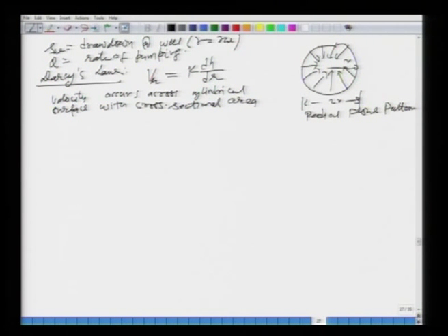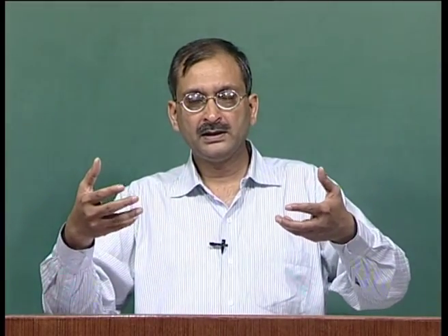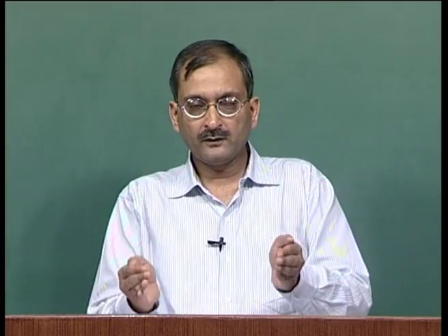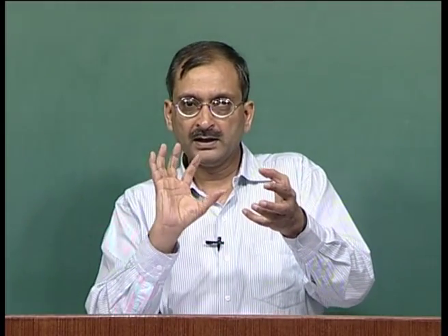Okay. So, if you are looking at it from the side now, this was the top, this is your cylinder. What is its height? This is your aquifer thickness B. What we are looking at is radial flow taking place towards the well, and if you take the cylinder of the complete depth of your confined aquifer, then you are looking at a cylinder whose length is B and radius is r.